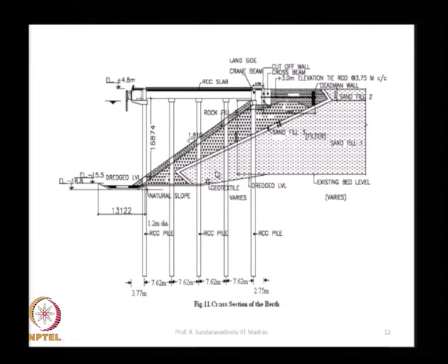Is this figure clear to you? We build the structure in open sea where minimum dredging is required. From this portion to the breakwater, as exists in Chennai port, we use sand fill, then some big size stones, which is the core stone, then we use armor stone, with a slope of 1 vertical to 1.8 horizontal. Then we anchor this below the bed level with some material which is as big as the armor stones.